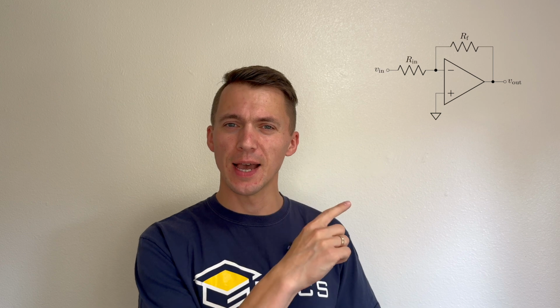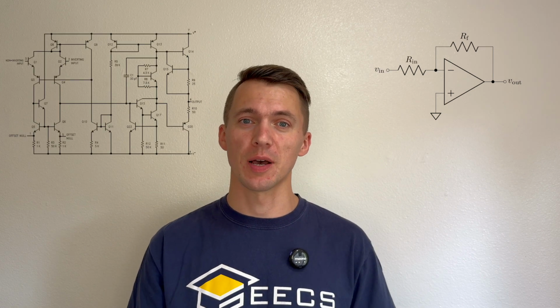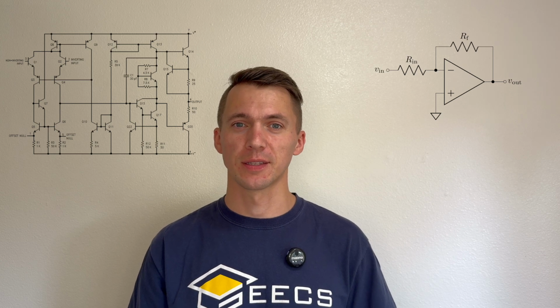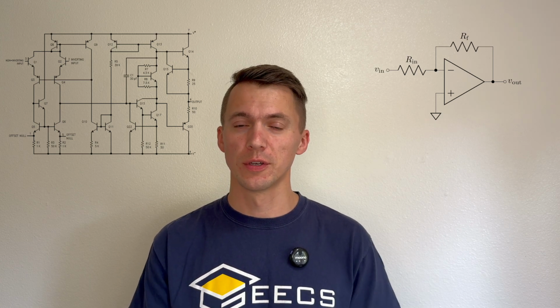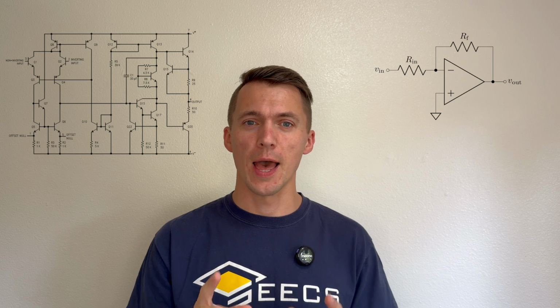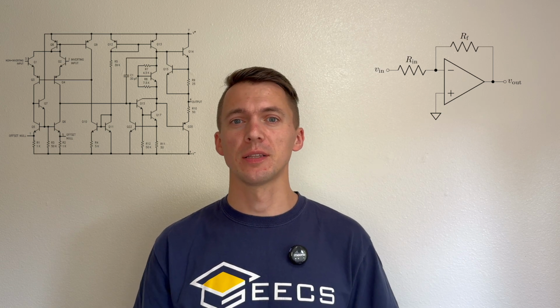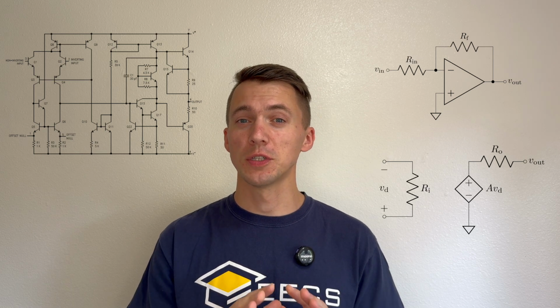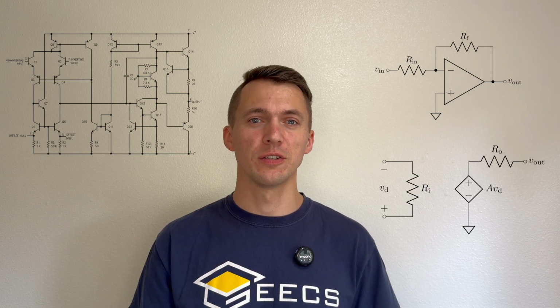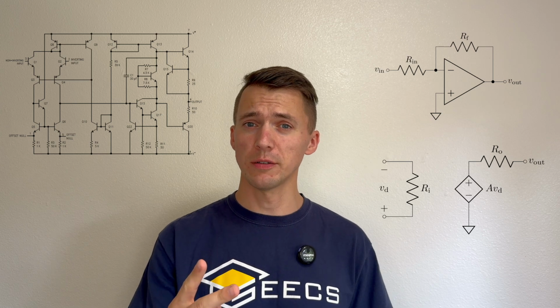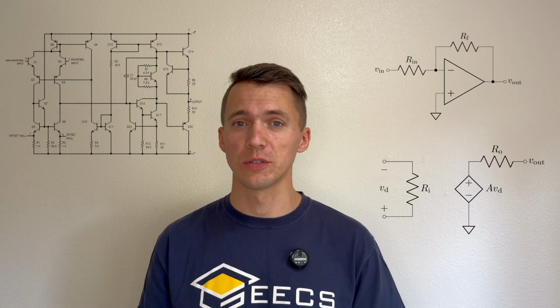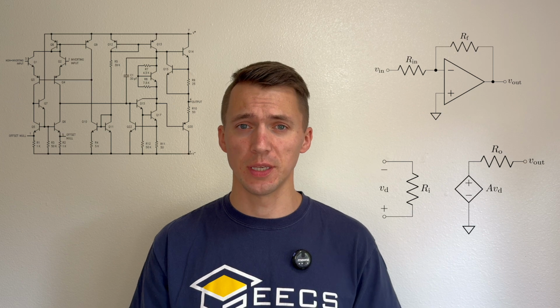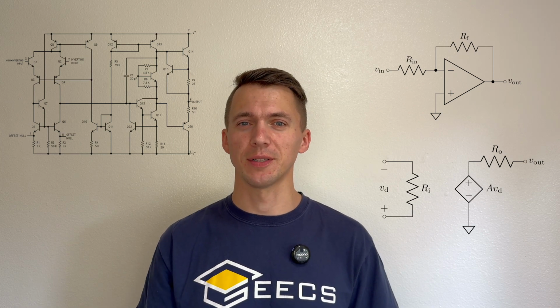I understand why. When you look inside this tiny little guy, you will find such a crazy circuit that might stop you from the further analysis. But I have good news. The first one, op-amp can be represented as a voltage-controlled voltage source. So instead of a bunch of resistors and transistors, you have just two extra resistors and one dependent source. The analysis becomes easy.